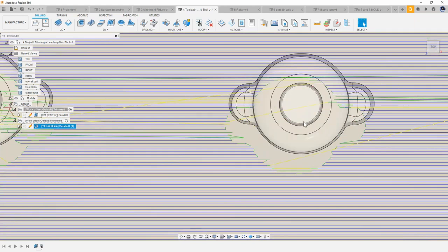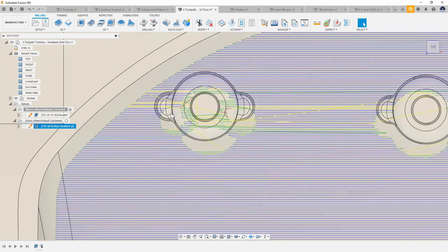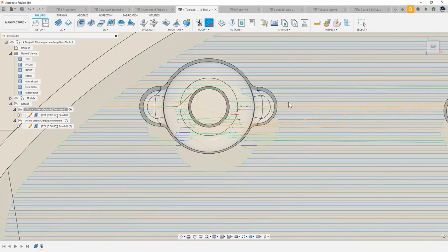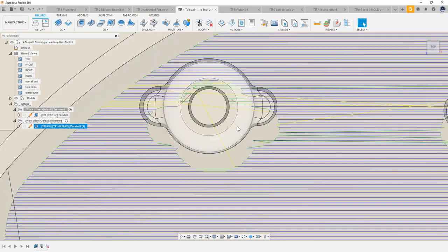Now that is the first way to do it, and this is a really custom way to do it, especially if you see something you don't like or if it's halfway on a toolpath segment. The other way is called delete passes, and delete passes works similar but a little bit different. It allows us to do things like a window selection here, and anything that I have encompassed in that window, you can see the selection was obviously different than that polygon, but it automatically grabs all those areas, and I can tell it to do the same thing, just trim them off. It will actually trim off that toolpath and give me my result.